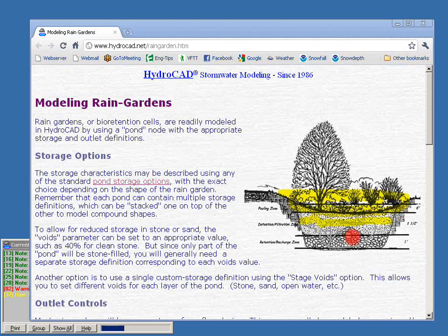So more complex setups are certainly available to you. In fact, the porous pavement UNH example that we discussed is similar to this in that we have a long TC for the travel time through a filtration layer, and then the water eventually enters a stone storage layer underneath.